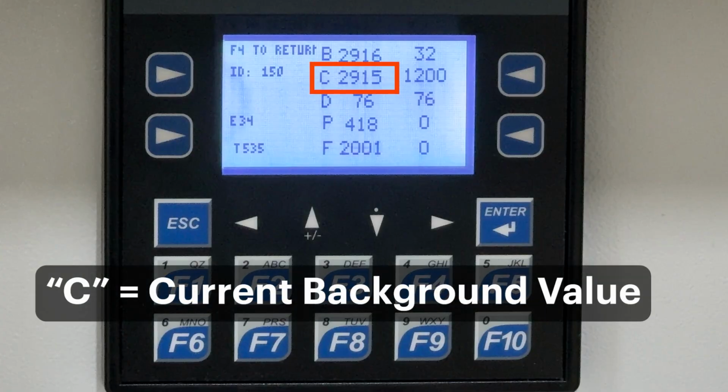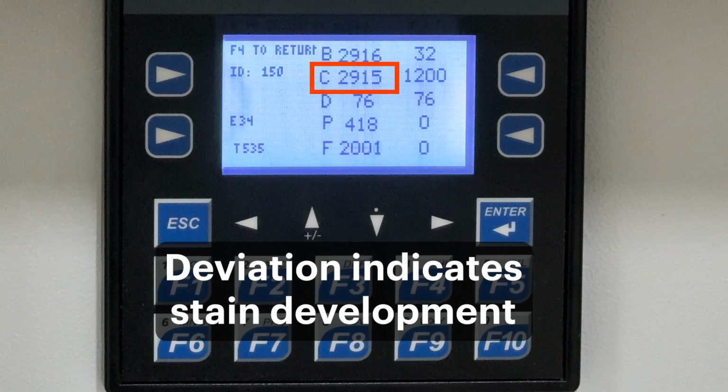C stands for the current background value and represents the amount of light seen reflected off the tape real time. This value updates every 4 seconds. If the C value begins to decrease from the B value, stains are developing on the tape. A small deviation over a long period of time indicates slow stain development and typically results in low concentrations displayed.